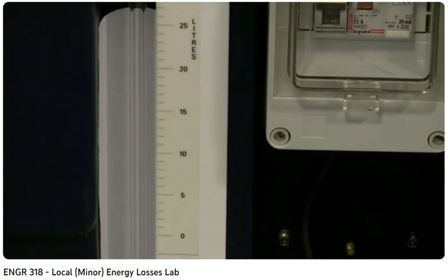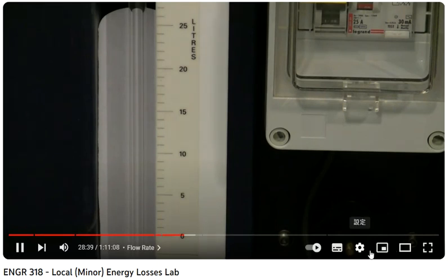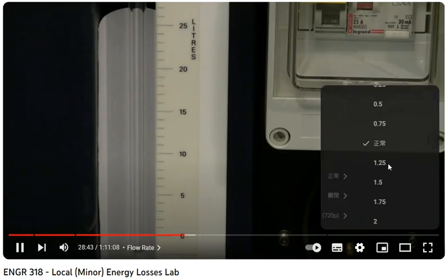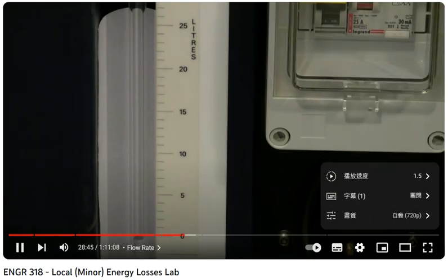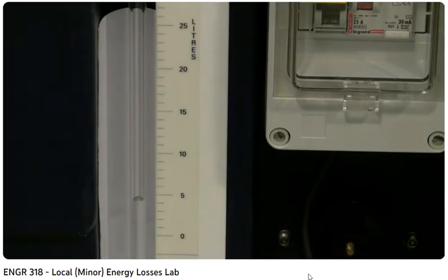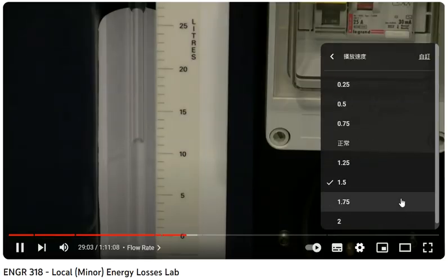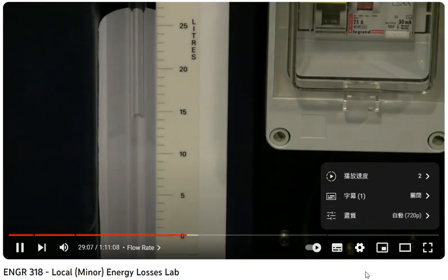I'll drop the ball. Have your stopwatches at the ready. And I'm just clearing my stopwatch so I can follow along at home. Okay, you need to indicate a certain volume collected in a certain amount of time. So it doesn't matter if it's from 0 to 25 or from 1 to 23, whatever you know that volume increment is, and the corresponding time it took for that volume to accumulate in the wet well at the bench.